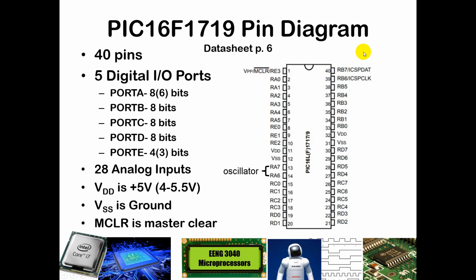We have on this PIC microcontroller 5 digital ports that can be used as either input or output. Now, each port does not mean just a single pin. In fact, we are using an 8-bit architecture in this PIC, and what that means is that most of our ports are actually 8 different pins that together form a full register that is 8 bits wide. Now, some of these pins cannot be fully used as inputs or outputs, so you do have some limitations.